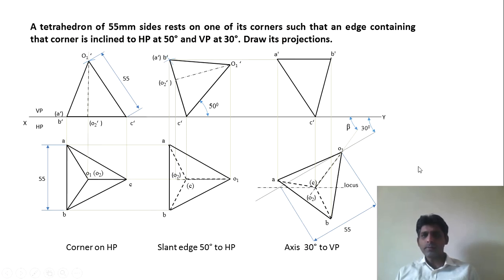Okay, so we have drawn the base, and this point O1 is here. This is the axis, and again what I insist to draw this final front view is that first mark all the points and draw the boundary lines. Boundary lines are always visible, as you can see in this case. They are drawn with continuous lines, and spot the farthest point. In this case A is the farthest point, so whatever is going to start from A is going to be hidden except for the boundary line.